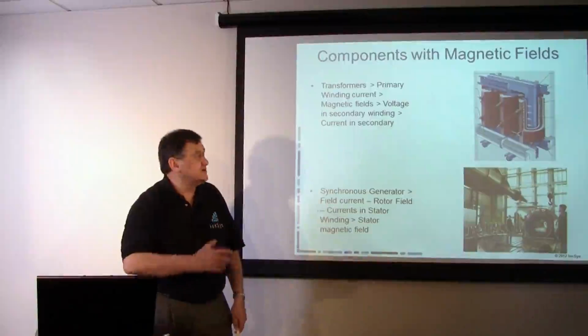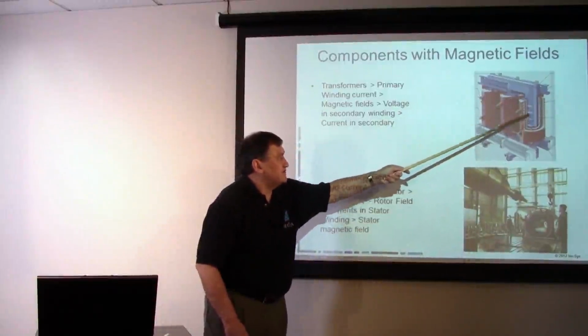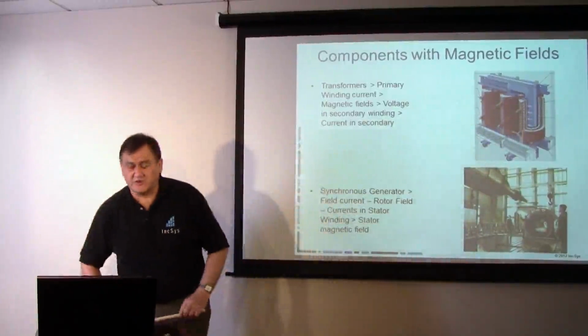And that's the whole idea, to increase the flux density, and that way you increase the effectiveness of one winding inducing voltage in the other winding. So transformers, as you energize them, they absorb megavars, and as you increase the power through them, they have a large megavar impact. And they are net consumers of megavars. A transformer, the megavars going in will always be less than the megavars coming out because they have a net loading effect.